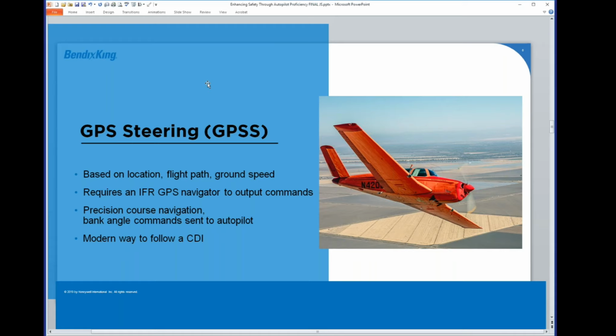So these GPS steering systems came along and gave you this little trick that kind of gamed the system and allowed you to put your autopilot in heading mode and then switch this thing on, and they interpreted what was coming out of the GPS for roll, and they fed it a kind of counterfeit deviation out of heading, and poof, the aircraft flew it.